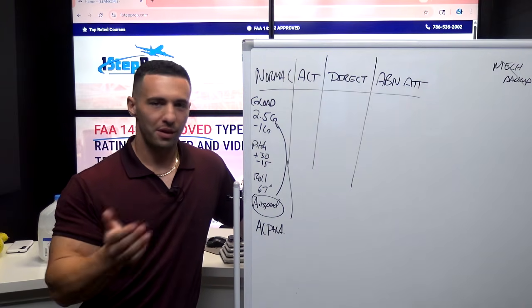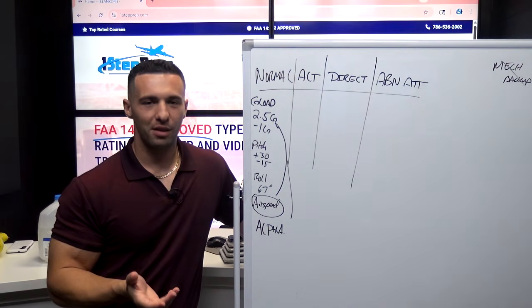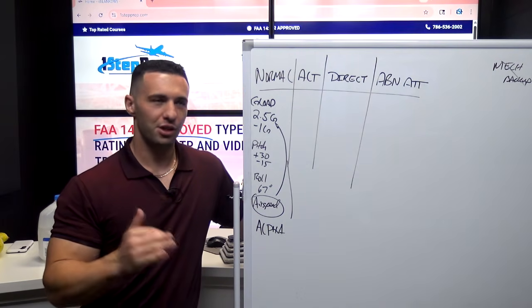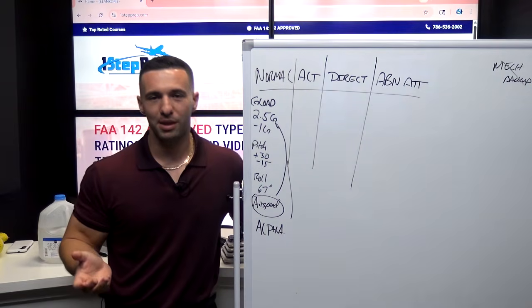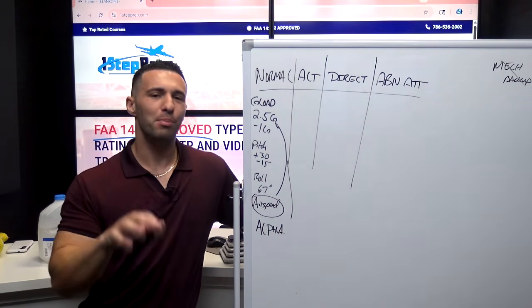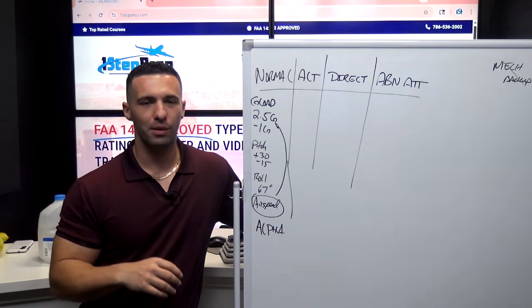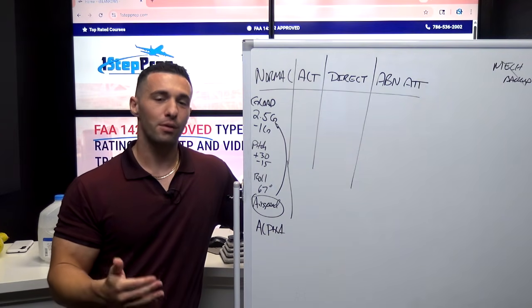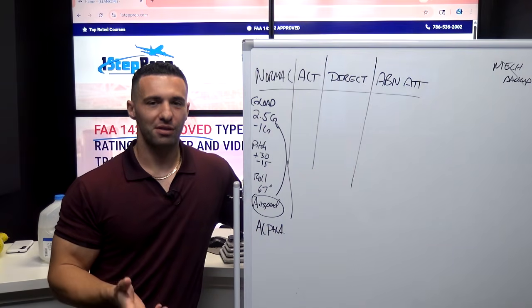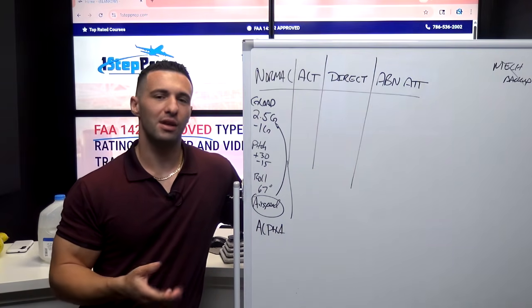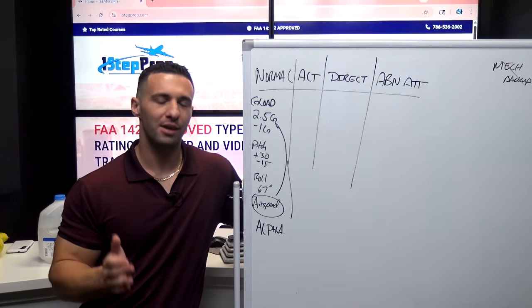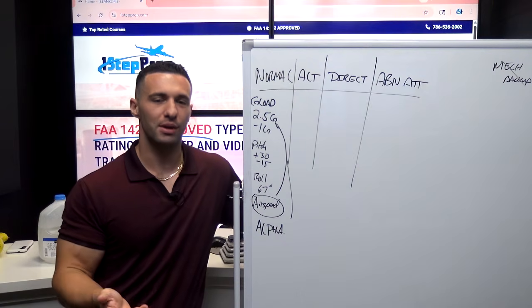And there's several things that it'll do, right? So the first thing it's going to do is disconnect the autopilot. And anytime we do stall recovery, or I should say approach to stall recovery in the sim, because in the sim we never do, unless you're an EET or UPRT in a type rating environment, we just do approach to stall recovery, and we recover at the first indication of a stall. And generally when we do our first stall of the stall series, the first indication is the autopilot disconnecting, which is a telltale sign and the signaling of the fact that we're entering into alpha prot.